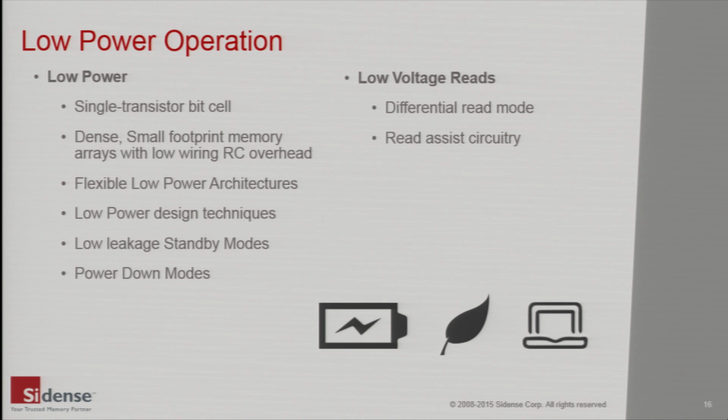As well as the low power requirement, it is often necessary to read OTP contents during low voltage conditions. Such conditions may be experienced at boot up when the supplies have not yet reached their steady state, low voltage sources, or just due to a decaying, aging battery. Under these conditions, operating in differential or redundant modes would be recommended again. Some newer designs feature read assist modes that integrate charge pumps directly into the bit or word line that boost the read voltage. Using such techniques allows read voltages close to core voltages.